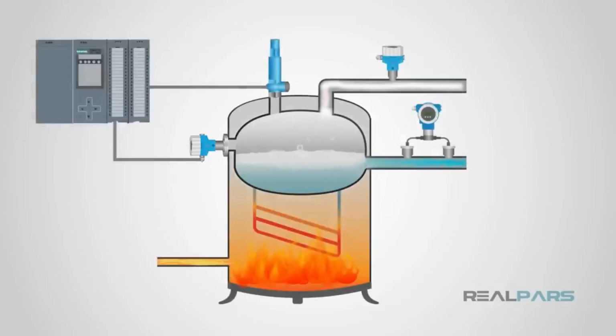Another purpose is to control when and where steam can flow and regulate its pressure. Steam can build up a pressure in a vessel and become dangerous. We can use the pressure sensor as an input device to open and close a control valve to keep the pressure and steam flow regulated. This only requires simple programming in the PLC to achieve this.